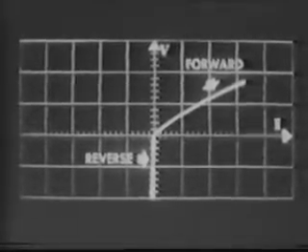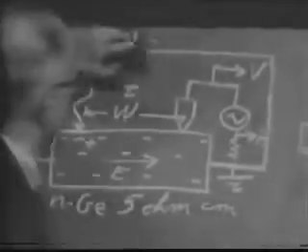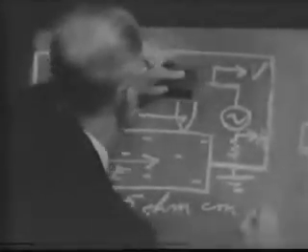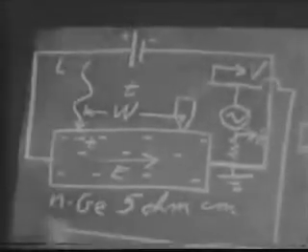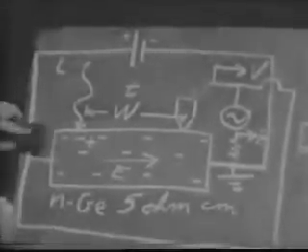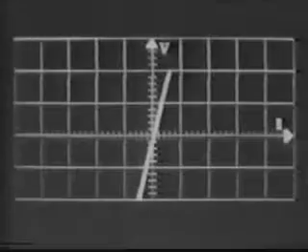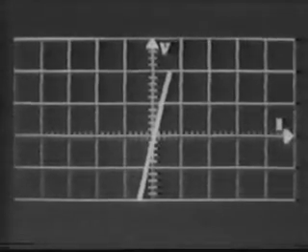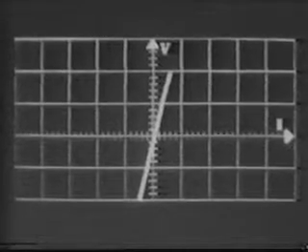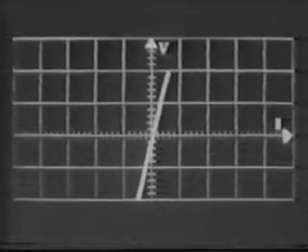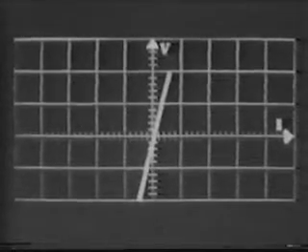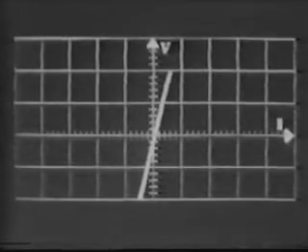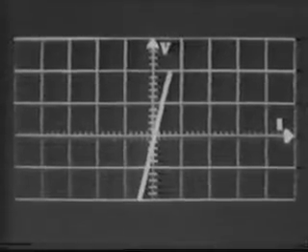We can show this by changing this connection from the point to the other end contact. The voltage current characteristic you now see is quite different from the previous one. You see then that the rectifying characteristic must come from the point and not from the end contacts or from resistance along the bar.